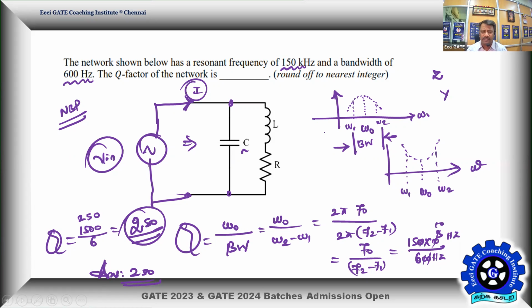I didn't talk about exactly what happens to the impedance, connecting straight to the problem, since Q is equal to the center frequency divided by the bandwidth. In filters, especially band pass filters, the Q is talking about the frequency selectiveness. It is actually a narrow band pass function. Around the center frequency of 150 kilohertz, you have up 300 and down 300 hertz, approximately.